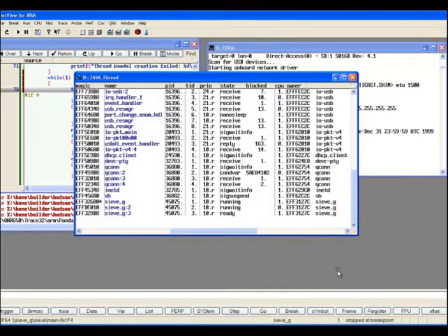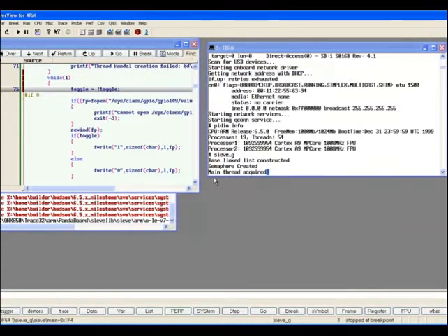Now in QNX it's a little bit different. In QNX, CPU really means the core. And because the thread window is more dedicated to the QNX terminology, inside the thread window the CPU means core. So it's a little bit confusing, but I hope you can get that this CPU means the terminology of QNX and this core is the terminology of TRACE32, but actually those refer to the same object. Okay, let's close that one.